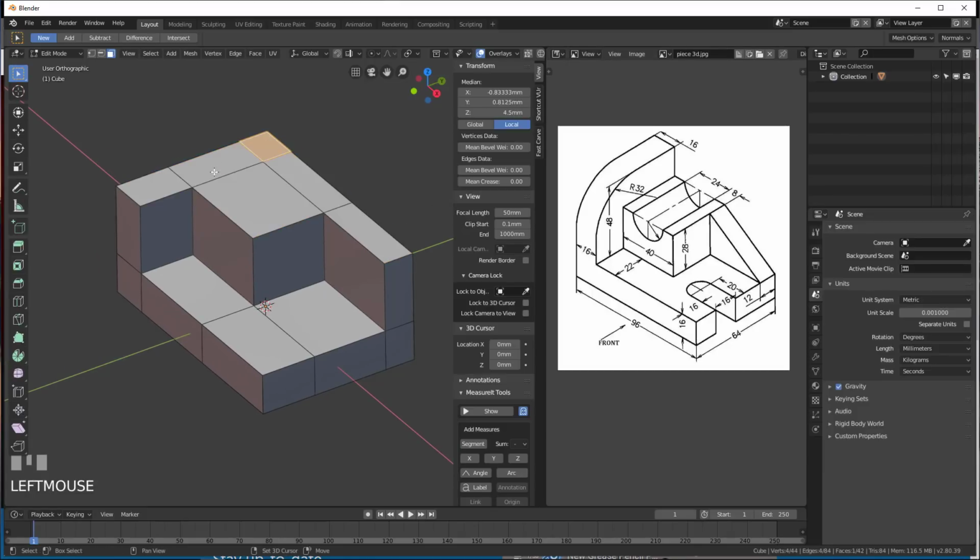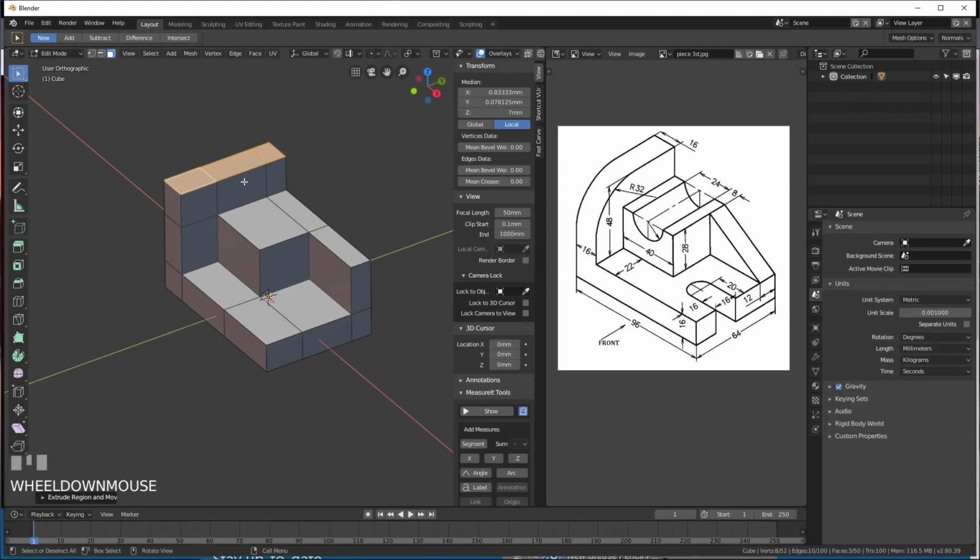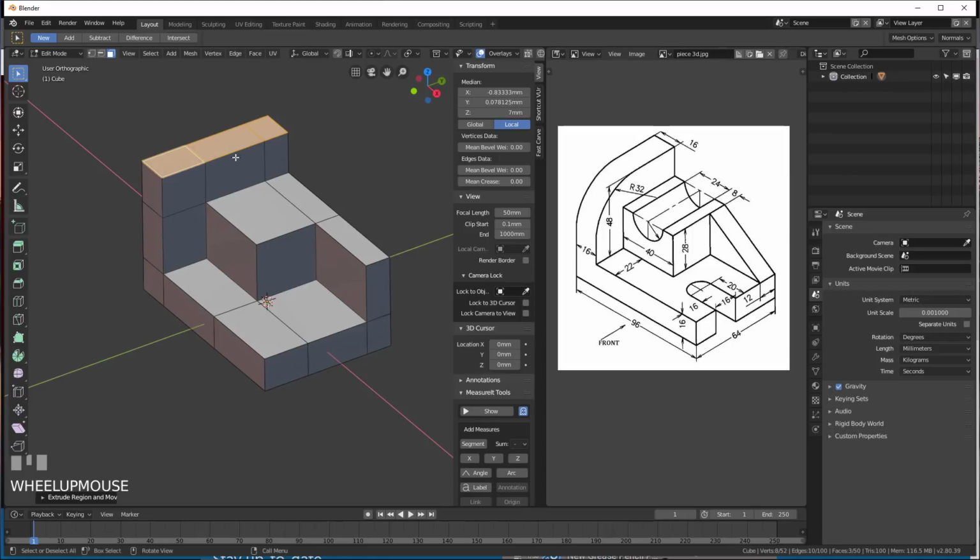And after we select only that part that will represent this part, and we see that it's 48 from the base, and we did extrude already 28, so still 20 to go. So extrude E20, and it will make this. So we have the global shape of our piece here. What we would like to do now is to make this round shape that we have, this beveling round shape that we have here.